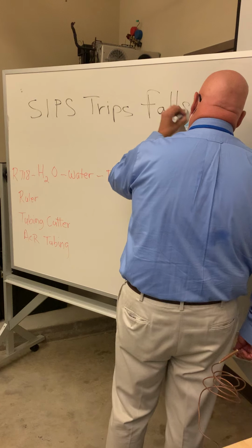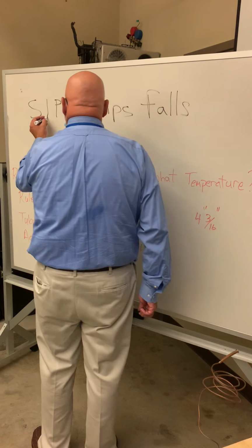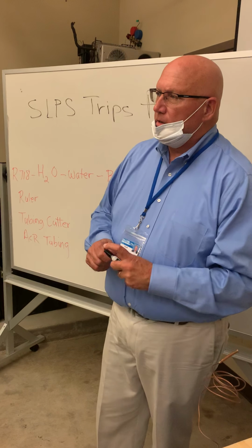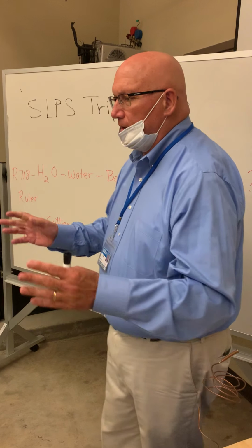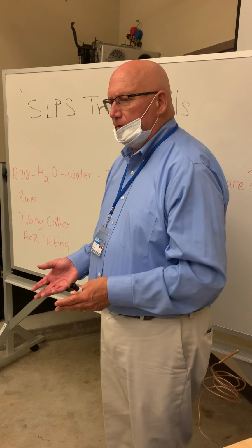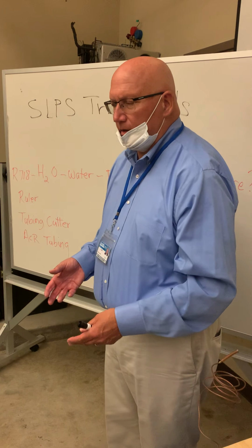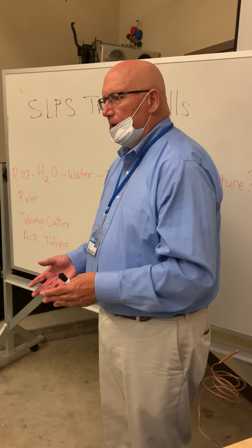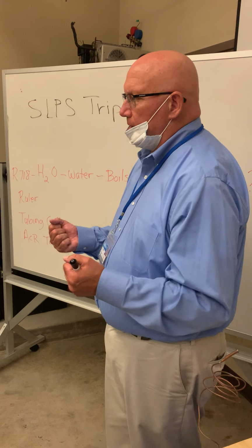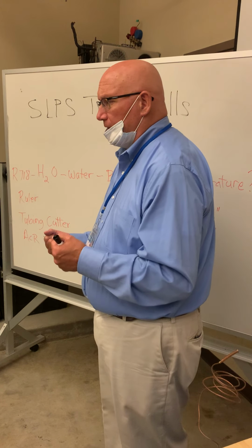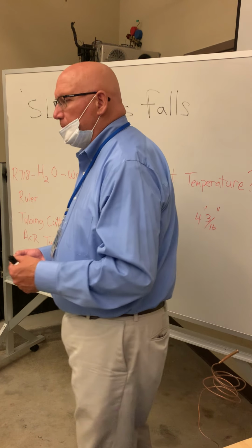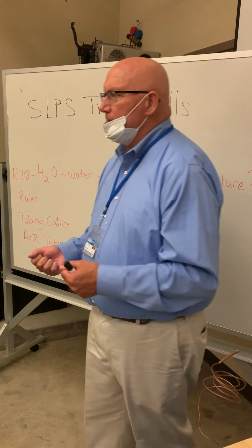the number one workplace accidents are what's called slips, trips, and falls. So right now, the shop floor looks really good. It's pretty clean. There's no cables on the ground. There's no acetylene tanks here. There's none of that sort of thing going on. But that's not normally the case. So if you're walking and you're carrying something and you're focused maybe on the weight of that thing that you're carrying, and if you don't look down, you may stumble your toe or you may trip on any of those number of things that you find.